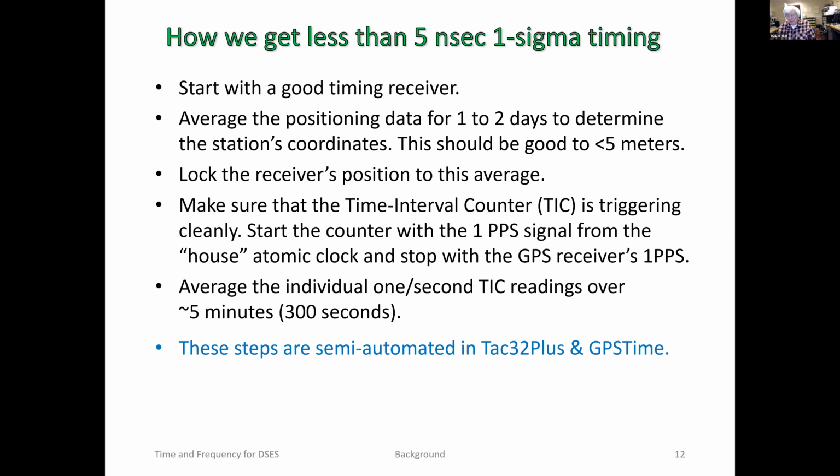The location that you get from a GPS receiver is not where the receiver is, by the way. It's the phase center of the antenna it's connected to. Right now, the antenna we're using for the time and frequency system is not where I would like it to be. It's just attached to the rain gutter in the building, but that's okay. It's not going to affect the precision time and frequency, but it does give us latitude, longitude, and altitude. That's where the antenna is.